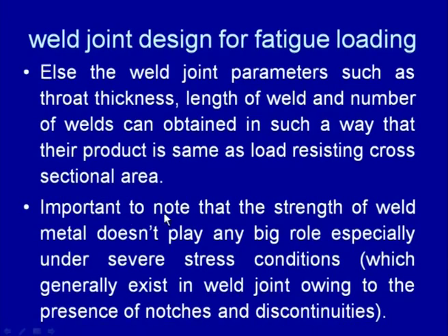It is important to note that the strength of the weld metal does not play any big role, especially under the severe stress conditions which generally exist in the weld joint due to the presence of the notch and discontinuities. So, reasonably good strength of the weld metal is found good enough for developing the weld joint for fatigue load conditions, but too high strength of the weld metal does not help in enhancing the fatigue performance of the weld joint appreciably. So, for designing the weld joint for fatigue loading, what are the important requirements?